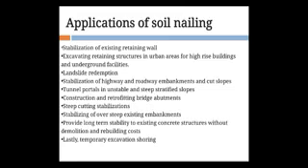Landslide remediation: in hilly portions there are lots of landslides, so we can avoid them by soil nailing. Stabilization of highway and roadway embankments, cut slopes, tunnel portals and unstable steep stratified slopes. Construction of retrofitting bridge abutments, steep cutting stabilization, stabilizing over-steep existing embankments, and providing long-term stability of existing concrete structures without demolition or rebuilding cost. Lastly, temporary excavation shoring.